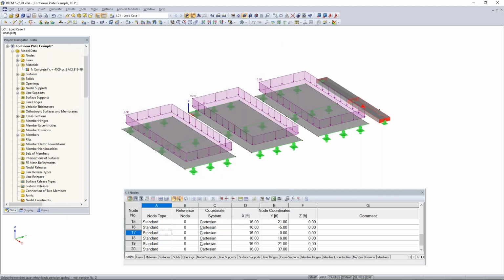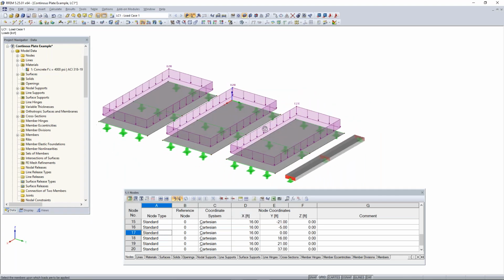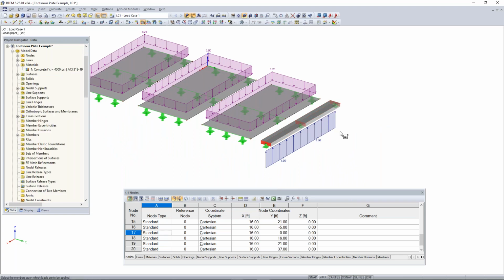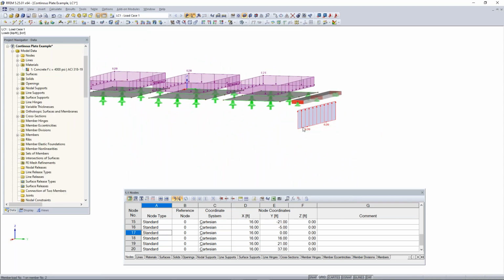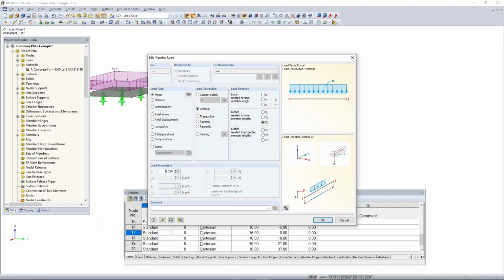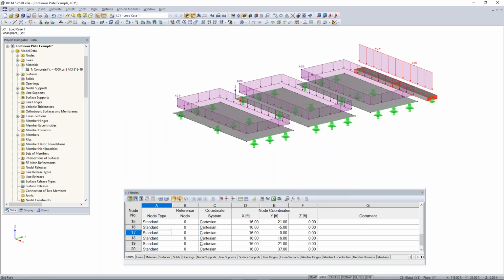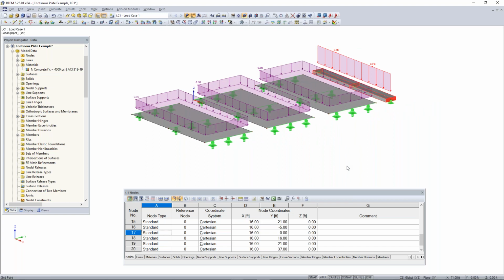So we'll click OK. And really, we're just keeping these loads the same so we can then compare our results and see the difference between both our beam here and our plates. So I'm going to change this to negative. And then we can now add in or edit our FE mesh.